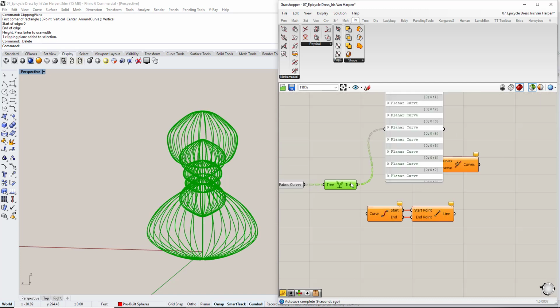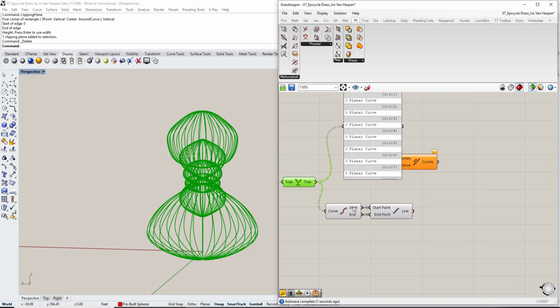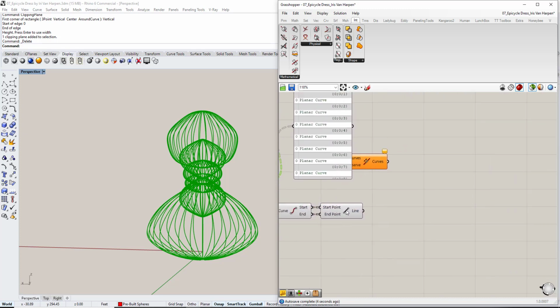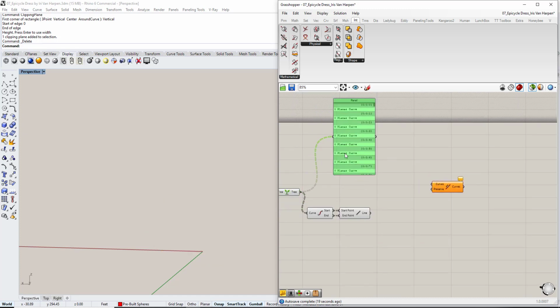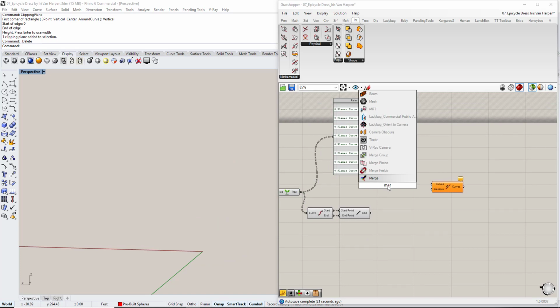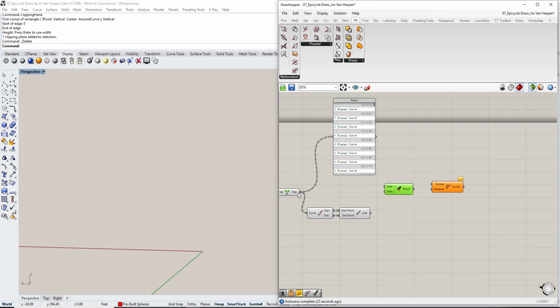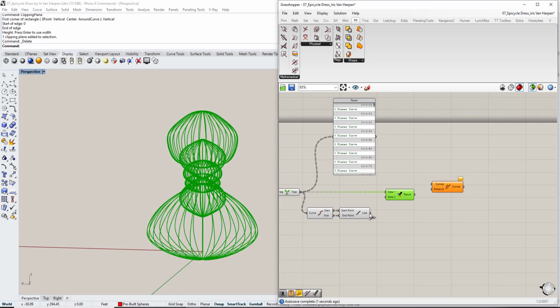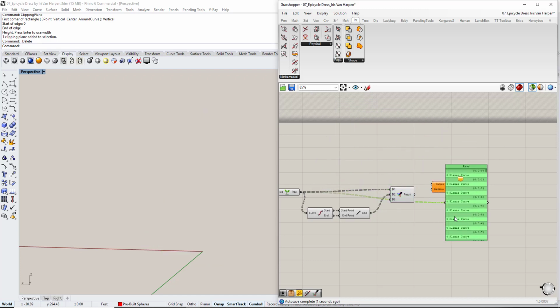This is each individual curve. So for each individual curve, I'm going to grab its individual endpoints, which give me 1 line, right? And if I hover over the output over here, look at this output. It also says that each item is in its own list. So there's multiple lists. Each list only has 1 item. That's perfect because now I can use the merge component and merge this original curve with this line, and let's see what this output looks like.